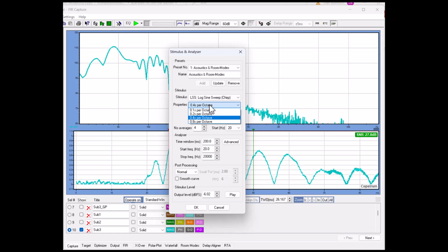Then we need to have a quite long impulse response. The rule of thumb is that the impulse response should be twice the length of the reverberation time. So this is 4 or 8 seconds we can choose between. We can use an accelerated sweep because we don't need high frequency information. We can use a low pass shelving filter, but it's not actually necessary because we only measure the subs.